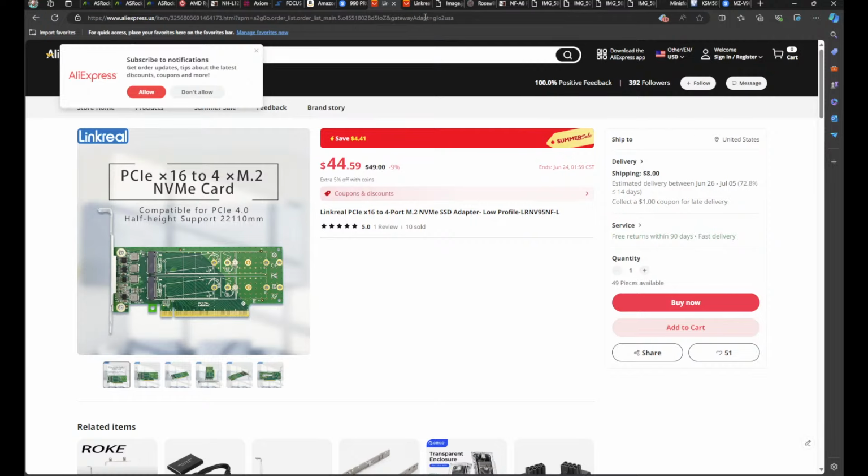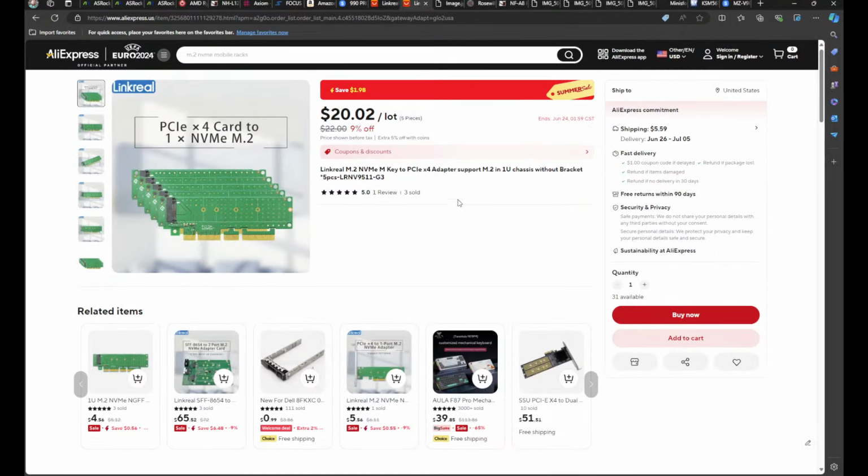Also, as I mentioned earlier, the motherboard only has that one M.2 slot, but I have two of these 1 terabyte drives in a RAID 1. Where did the other one go? Well, right above that 16x slot on the motherboard, there was another 4x PCIe 5.0 slot that goes straight to the CPU. So I bought this other riser card for a single M.2 NVMe drive, and that one and the one on the motherboard are together in that RAID 1 mirrored set. This is the card I bought for that.